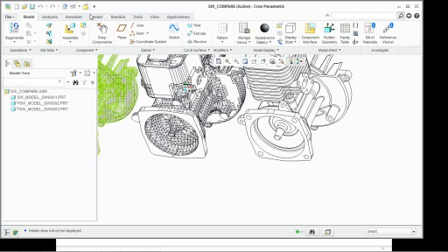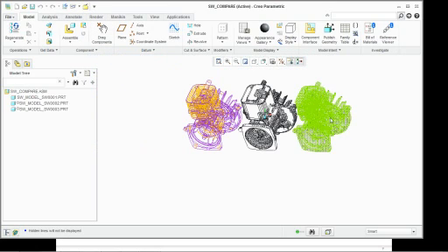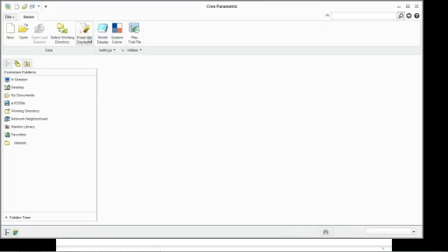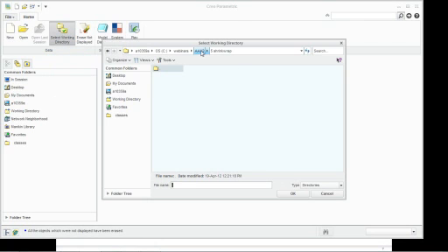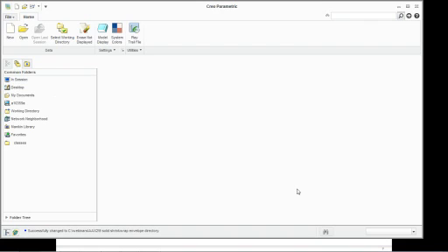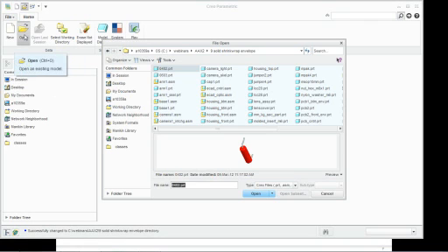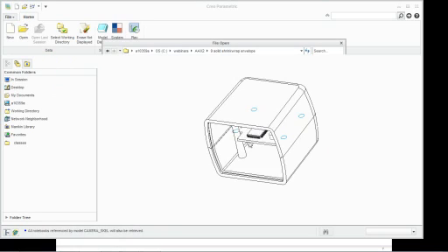So now you're thinking, well, what's the point? Why would I want to use these? I'm going to flip over to another example now. And this is the camera example that I talked about a couple weeks ago. So we're going to select the working directory, and now we're going to say we want to go to solid shrink wrap envelope. I'm going to create a shrink wrap and actually use an envelope to put it into an assembly. So now we're going to open, and we want to go to, let's see here, camera1.assembly. There it is.